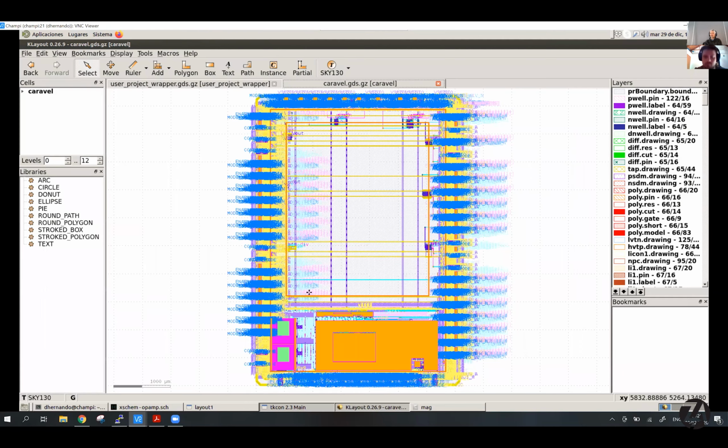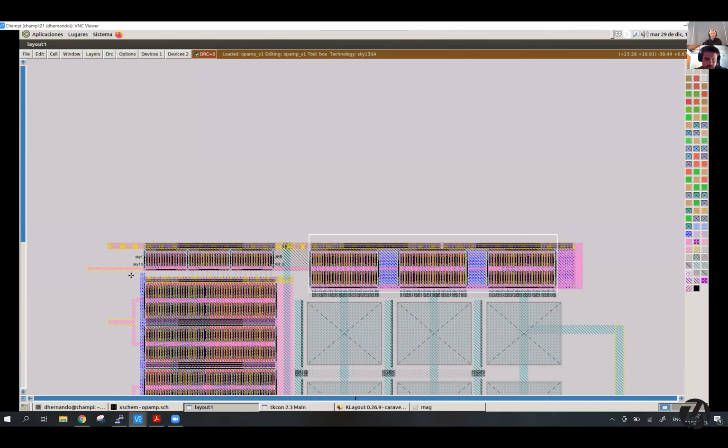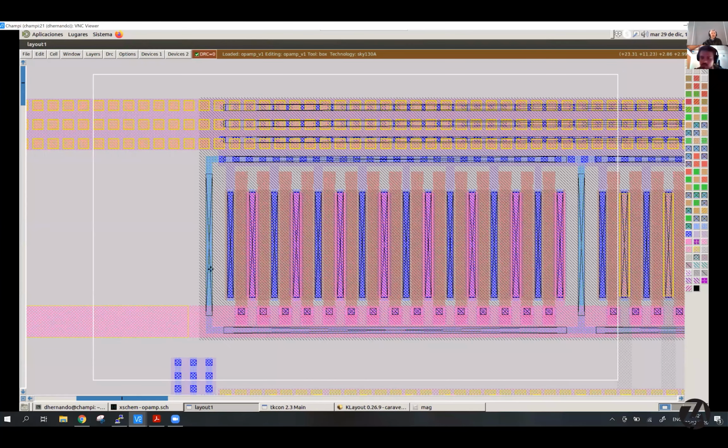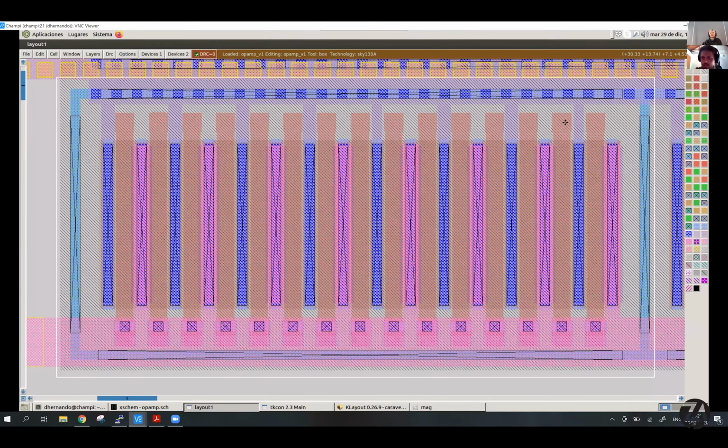And I see on the outside, on the output, you've got 150. So those are presumably the really big shapes. Here you have 150 transistors. Here you have the 15 transistors. Could you just zoom in a little bit on that? There, that's good. So here you have 15 transistors, and these are fingers, because instead of having 15 separated transistors and connecting them, I am overlapping drain and source from the transistor. So that's a finger.